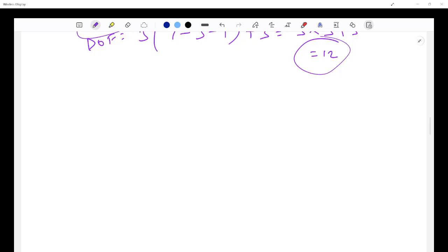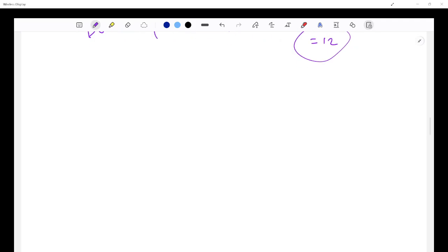So this 3 slider mechanism is over constrained. It has dependent constraints. The formula gives us a wrong value. So our actual degree of freedom is not the same as the computed degree of freedom. But the question explicitly says as per Grubler-Kutzbach criterion, so we must use pure counting without correcting for redundancy.